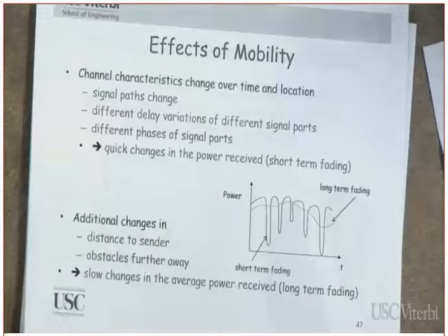The dynamic range of a receiver is the difference between what? The highest signal power that the receiver can process, are you following, without getting blocked. Getting blocked means getting saturated. Minus the lowest power that it can sense. Are you following me or not? This lowest power, by the way, we will refer to later on as the receiver sensitivity. The receiver sensitivity is governed by the noise level, whereas the maximum power is governed by the nonlinearity in the system. Do you understand?